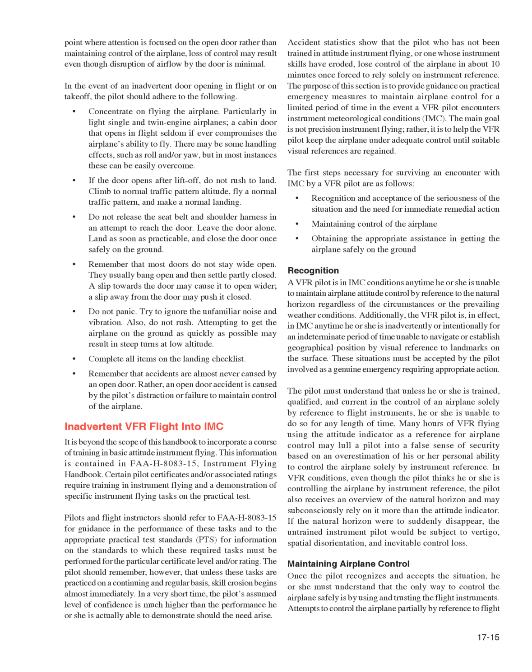In the event of an inadvertent door opening in flight or on takeoff, the pilot should adhere to the following. Concentrate on flying the airplane. Particularly in light single and twin-engine airplanes, a cabin door that opens in flight seldom if ever compromises the airplane's ability to fly. There may be some handling effects, such as roll and or yaw, but in most instances these can be easily overcome. If the door opens after liftoff, do not rush to land. Climb to normal traffic pattern altitude, fly a normal traffic pattern, and make a normal landing.